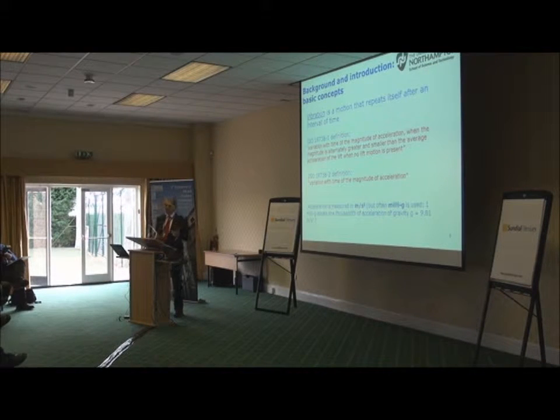Okay, so we measure vibration through level of acceleration. However, very often we are concerned also with velocity and with displacement. And we know that the ride quality is affected by jerk. So we have a number of parameters that contribute to how we assess the influence of vibration on ride quality and what we feel in the lift. We measure acceleration in meters per second squared, or milli-Gs, velocity in meters per second, and typically displacement in meters.